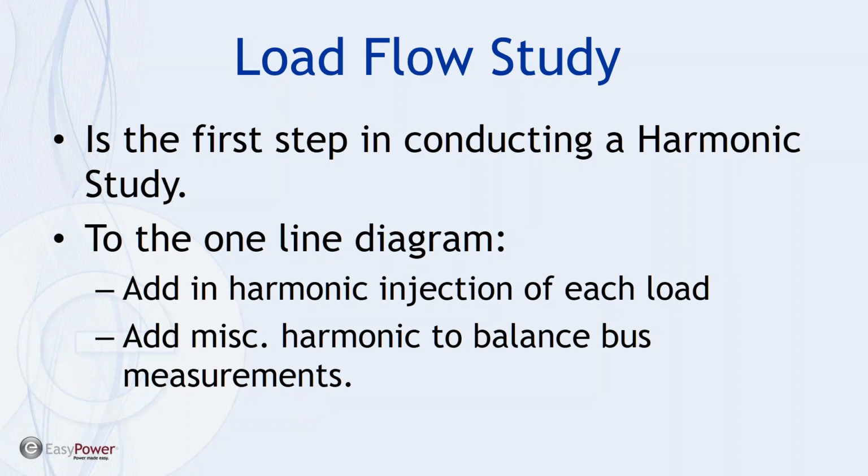So having a load flow study complete and up to date is a big part of it, because from that, if we have not done modeling that includes harmonics, we can add in the harmonics contributed by each load, and the tools can anticipate or compensate harmonic contribution based upon the power flow and percent usage as far as capacity.